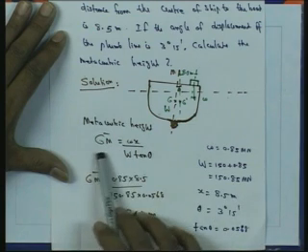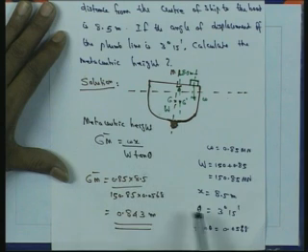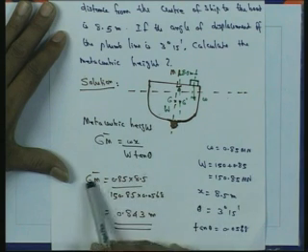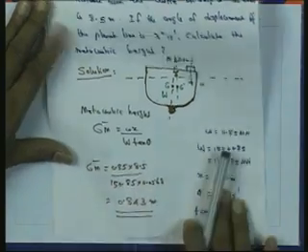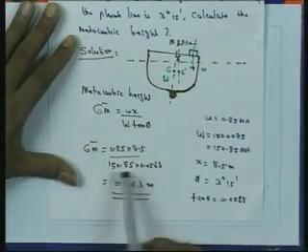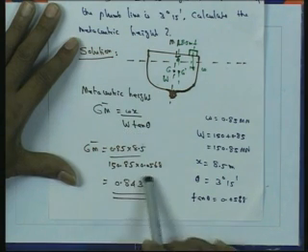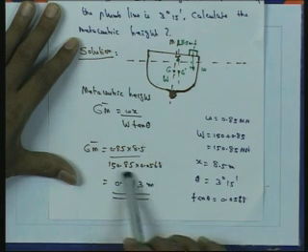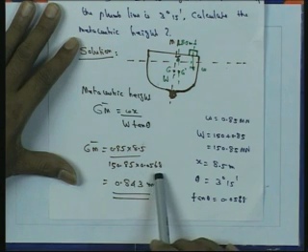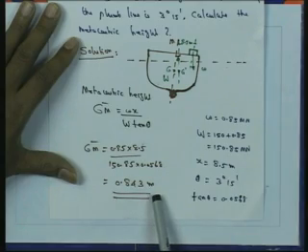So, the metacentric height GM is equal to small w x divided by capital W tan theta. Here GM is equal to 0.85 multiplied by 8.5 divided by 150.85, the total weight, into tan theta. Tan 3 degrees 15 minutes is 0.0568. So 150.85 multiplied by 0.0568, from which we get the metacentric height as 0.843 meter.